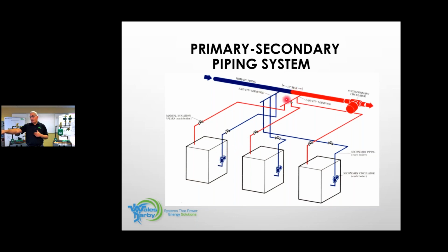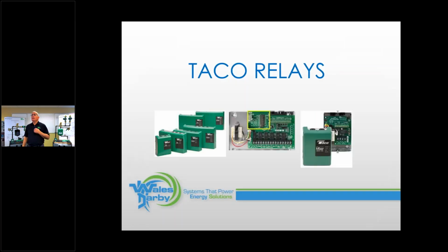Here are our closely spaced T's, and we've just extended them out because what did we do as we piped in these 3 boilers? We piped them in as a reverse return. This way we get even flow across the boilers. All right, very important, something that you can do out there on a smaller scale, commercial job, that you guys can prefab this and bring it to the job. If you need any assistance with this, let us know. Give us a call.